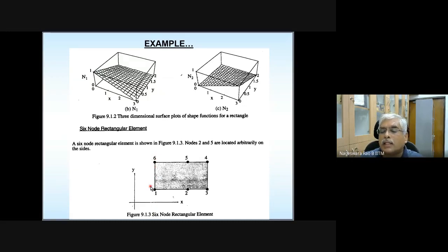So that is how you can write the shape function expression for N1. Similarly, you can write for N2. The N2 shape function expression is going to be x minus x1 multiplied by x minus x3, divided by x2 minus x1 multiplied by x2 minus x3. And again multiply this with a fraction, y minus y5 divided by y2 minus y5. So that is how you can write it, and after getting these expressions you can plot them here.